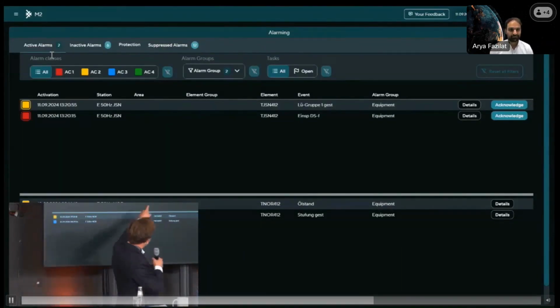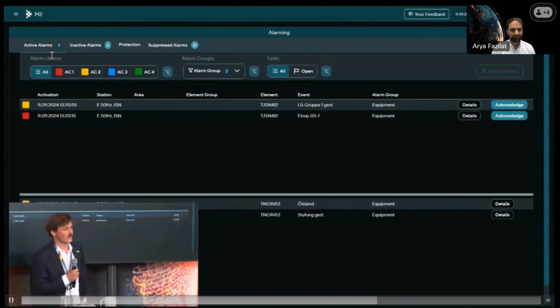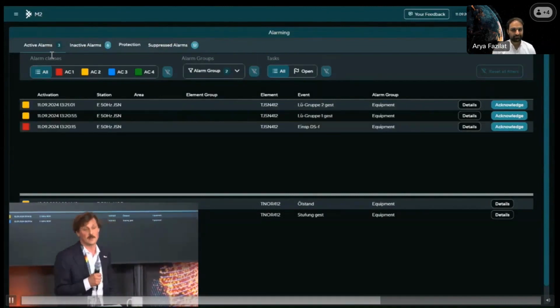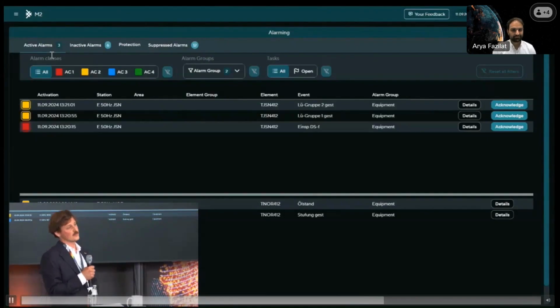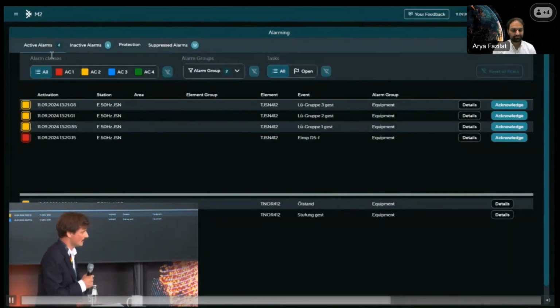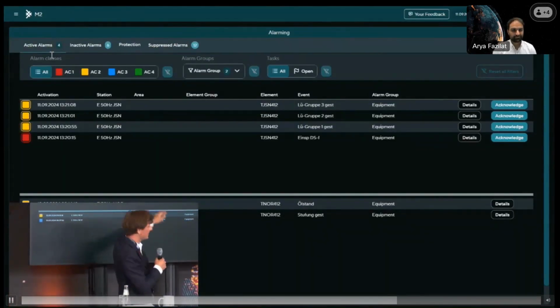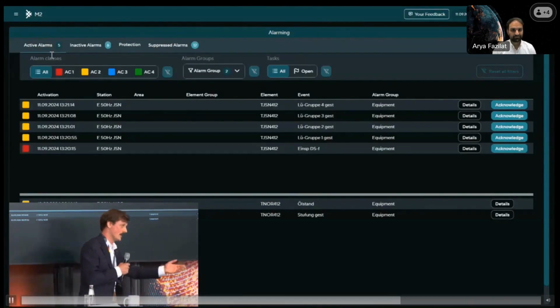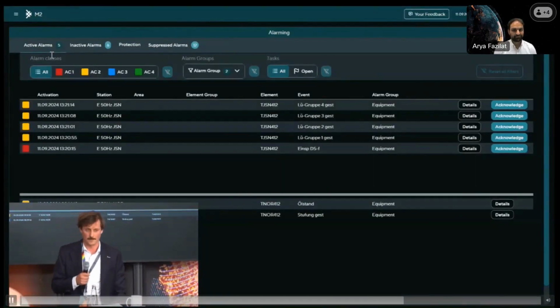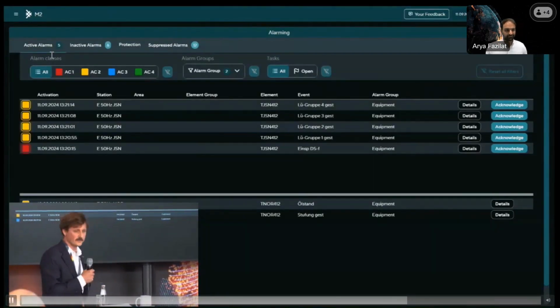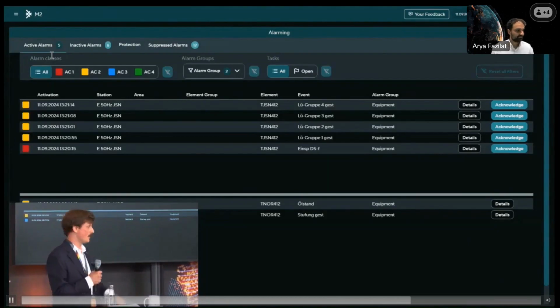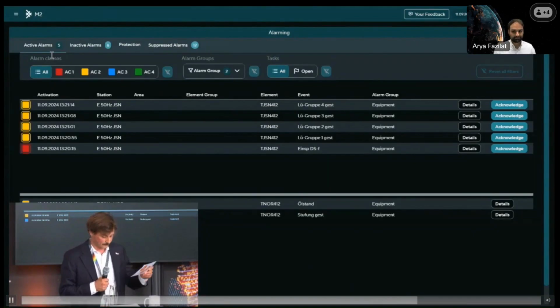Einspeisung Drehstrom fehlt means that the transformer has lost its auxiliary power feed-in, a situation to which operators must respond with highest priority. In accordance with the IEC alarm management standard, each message needs to be acknowledged by an operator, in our case, by Mirko, which means that someone is actively working on a solution, be it by direct controls or be it by delegations to other teams.